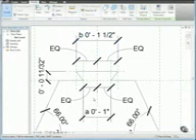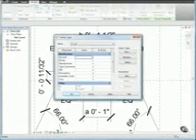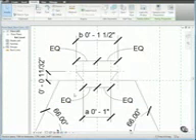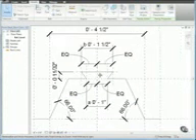Next, let's define a WR parameter. From the Family Properties panel, click Types. In the Family Types dialog, under Other, for WR, type 4.5 inches. Then click OK. Then select the dimension shown, and on the options bar for Label, select WR.